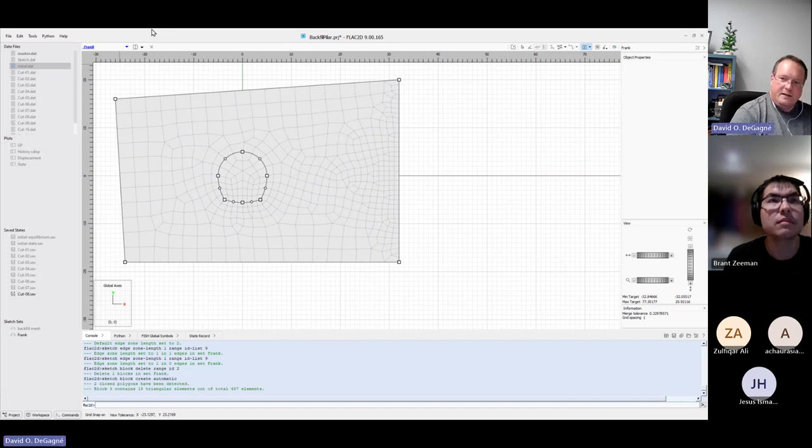And then we don't have it yet in FLAC2D, but in the previous version of a different product along the same lines, a 2D version called FLAC, we had a tool that would let you do remeshing. So essentially when it starts to sense these illegal geometries, these weird things happening to the zones, it will actually remesh the zones finer at that point, and then it automatically will transfer all the displacement information to the new zones and the stresses and all that sort of thing. That's something that we will be adding to FLAC2D, but it didn't make it in this year's release.